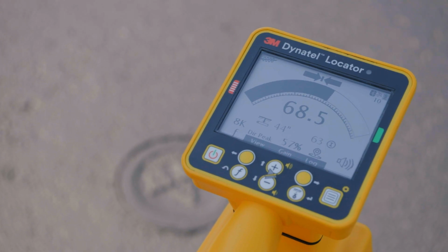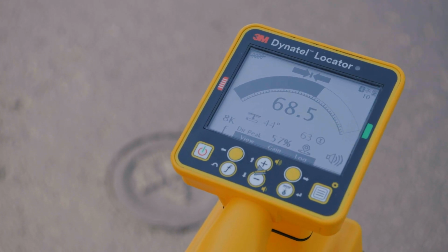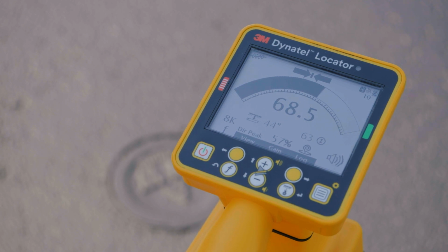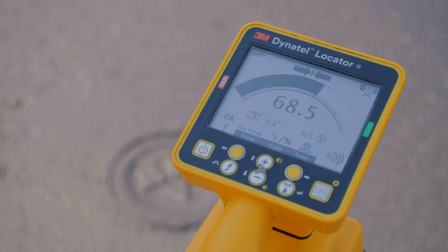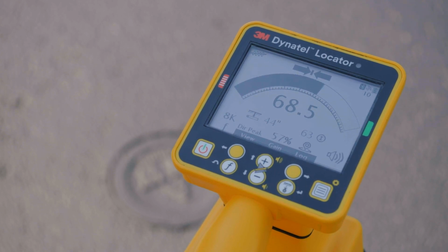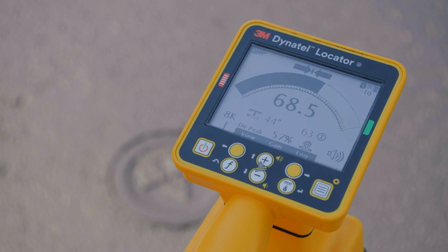When the middle antennas are centered over the electromagnetic field, both arrows will appear. The numerical signal level should be at its highest value. The bar graph should be almost closed, and both arrows should be displayed when locating a target with an undistorted electromagnetic field. In this view, the depth and relative current will be displayed when over the path.